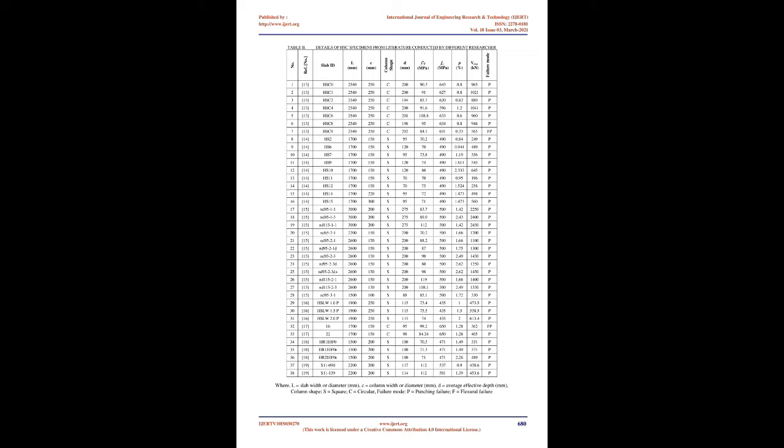Data collection. Punching shear tests can be done on either a multi-panel structure or on isolated slab-column connections. Multi-panel tests are time-consuming, expensive, and it is difficult to determine experimentally the shear and moments applied in individual connections. Isolated slab-column connection tests have the problem that the boundary conditions may not be realistic.